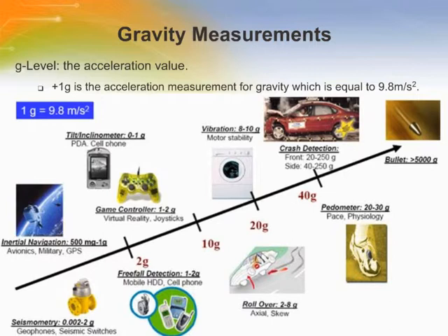Freescale has acceleration sensors with detection ranges from 1.5G to 10G in the low G portfolio of accelerometers, 40G to 100G in the medium G portfolio, and 150G up to 250G in the high G portfolio.